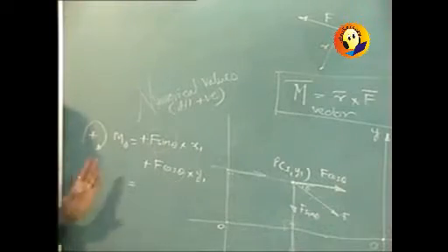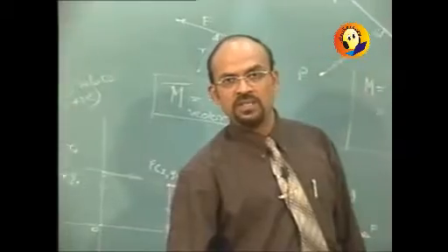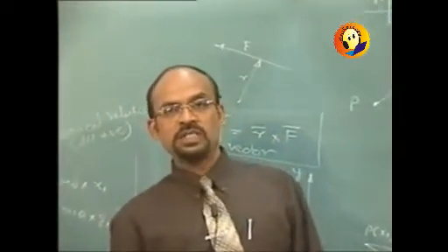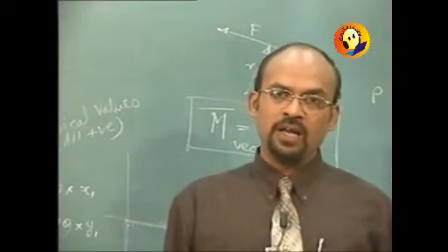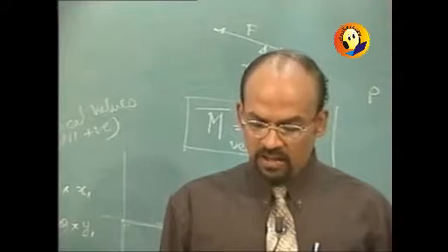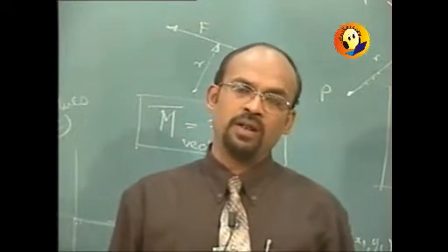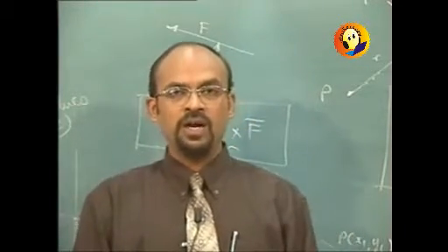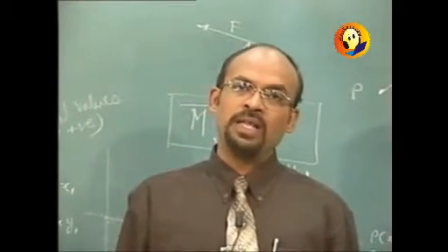So this was the very base that we will be requiring for our next topic, which is related to the equilibrium of rigid bodies, where the forces are not concurrent forces. And if they are not concurrent, if there is offset, then these forces will also result in rotation of that particular rigid body, and even that rotation should be prevented. The angular displacement should be prevented, and then only the body will be in equilibrium.